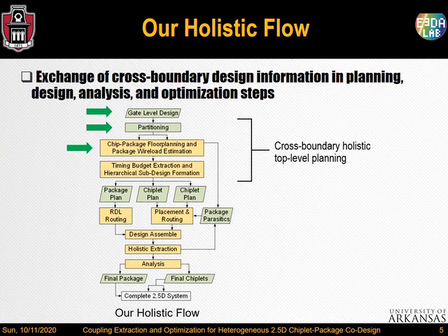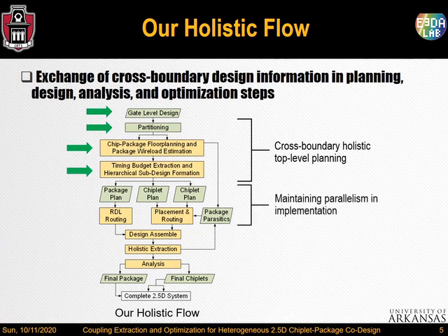Based on the package routing, package wire load is estimated. Signal assignments of chiplet pins are performed based on a greedy strategy. Using this top-level plan, timing budgets are extracted for each part of the design and they are separated into hierarchical sub-designs. These chiplet and package sub-designs are implemented in parallel. Though at this step, they are designed separately in their own design environments, the constraints imposed by the top-level plan are active throughout the process.